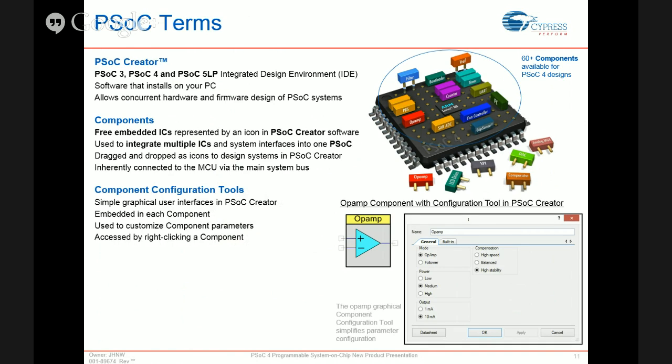Before we start doing that, just a quick few PSoC terms that we'll use often enough today that I want to mention them and define them up front. PSoC Creator is our IDE. It's a free download from our Cypress.com website, and it's a common integrated design environment for the entire PSoC platform of PSoC 3 devices, PSoC 4 devices, and our ARM Cortex-M3 based PSoC 5 LP devices. PSoC Creator allows you to do concurrent hardware and firmware design. Not only does it have that schematic view that we'll see in a few minutes today to design your hardware, it also does all of your firmware development like any other IDE.